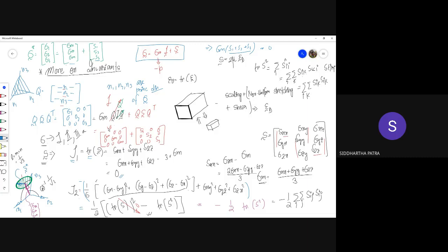So on those densely packed planes, the close packed directions are essentially where the atoms, when modeled as hard spheres, are touching each other. So together they make for 3 times 4, 12 slip systems. We discussed that in probably the second class. Okay, go back to that class right there.